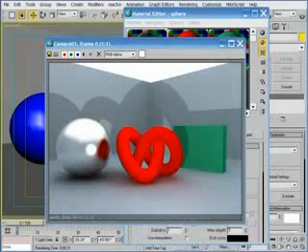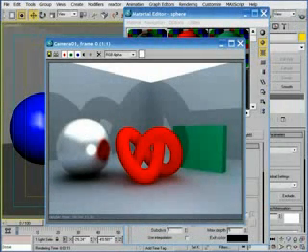And in fact, we see a very rough looking surface, almost like frosted glass. Now this may actually be a desirable side effect and a way to rough up the surface even more than by just reducing the reflection glossiness. The default value of 8 provides decent quality, but for really grainless reflections, you might want to try values up to 20.